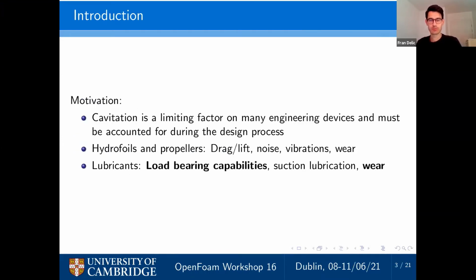So the motivation behind this work is quite clear. Cavitation itself is a limiting factor on many engineering devices and must be accounted for during the design process. For instance, the maximum velocity of America's Cup sailboats is determined by the onset of cavitation on the hydrofoil. As well as change the lift and drag properties of the hydrofoils, cavitation induces noise, vibrations, and wear.